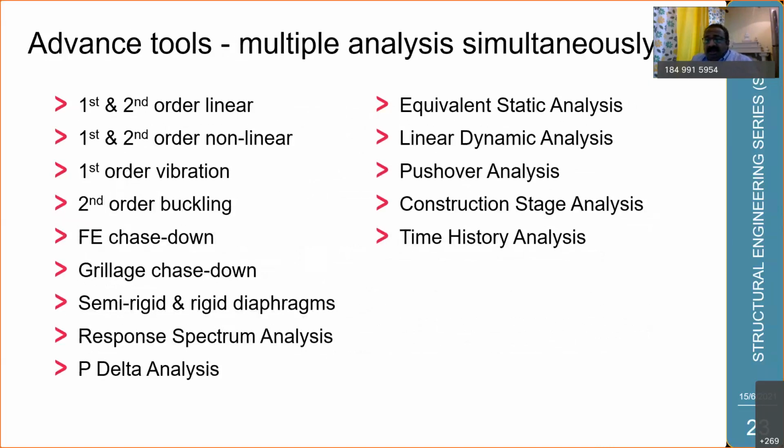And the analysis, the various steps of analysis are available. Starting from the first and second order linear, non-linear, vibration, buckling, the FE chase down, the rely chase down, semi-rigid, rigid diaphragms, the response spectrum, P delta analysis, the equivalent static analysis, linear dynamic analysis, pushover analysis, the construction stage analysis, and the time history analysis.